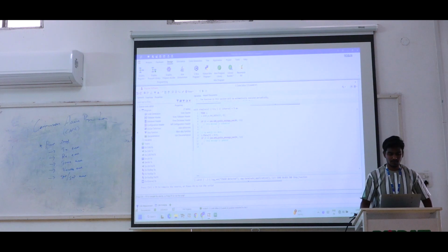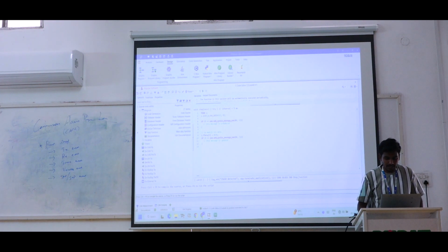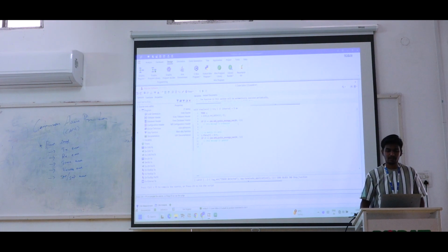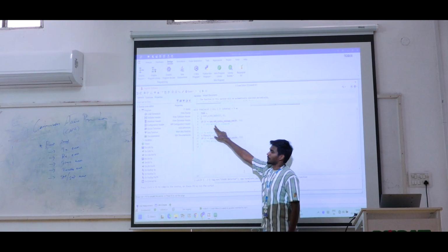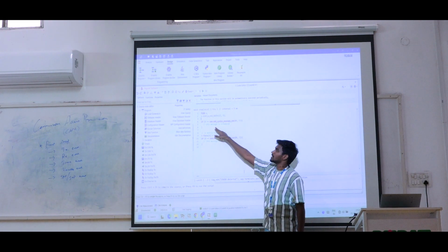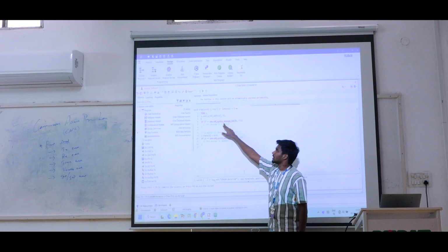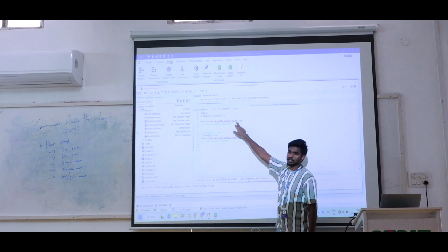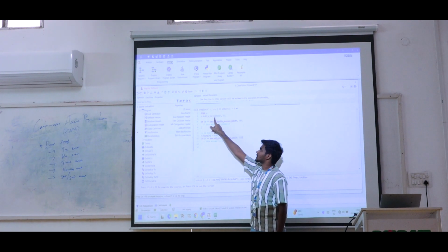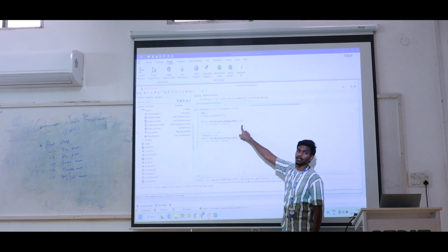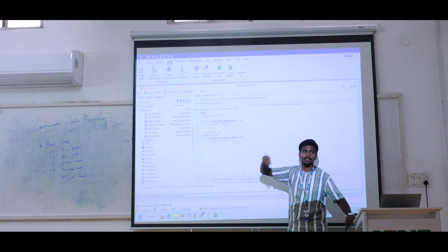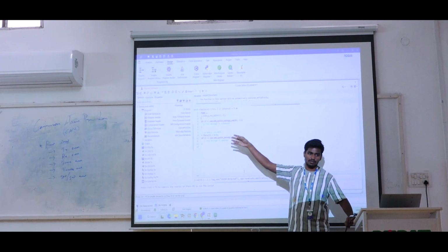They mentioned: if 0 is equal to com.add cyclic message can ampersand of t comma 5. This line says it is going to communicate, sending the cyclic message of CAN. The CAN ID is taken from the address of t, which holds the ID number 123 and DLC 8. The 5 is the periodic time, so every 5 milliseconds you have to transmit the message.